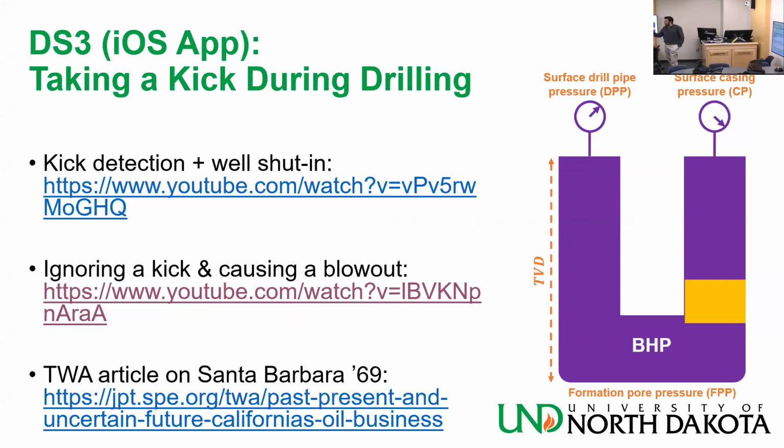Also depends on the clearance that you have in the annulus. How big is the annulus? If it's a very big annulus, it needs a lot of gas to get taller and taller because it's the height that matters. The problem is that even if you shut in the well and you're dealing with a gas kick, you have a fluid whose density is lower than the mud. So it's gonna want to rise on its own.